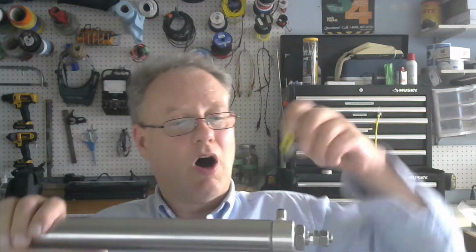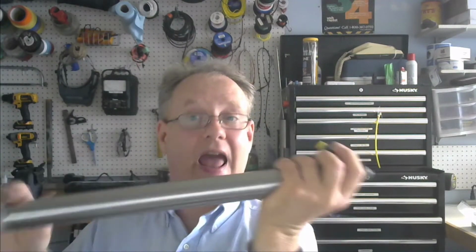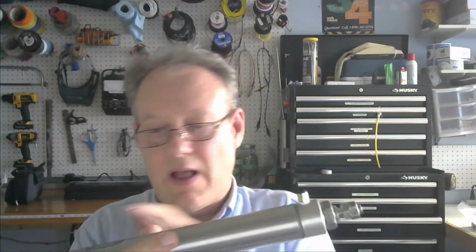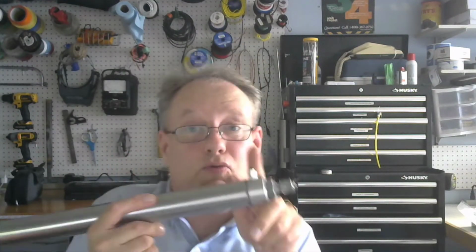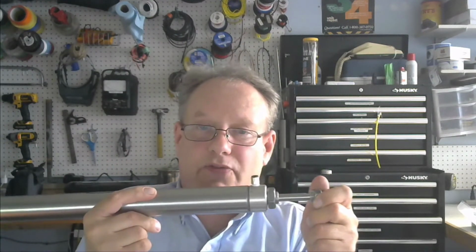So if we want a nice even motion, what we're going to do is put a non-return throttle valve or a metering valve on the output. And now what's going to happen is that as that air is leaving here, it's actually under pressure to some degree because it's being throttled. So that air that's coming out of here is getting throttled, and then as it's getting throttled, there's a little bit of back pressure, and that back pressure is actually slowing my cylinder down.